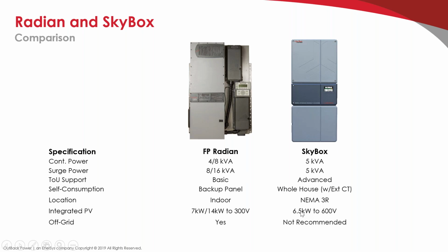The Skybox, you can have up to 6.5 kW connected at 600 volts. There's two PV inputs, but they're parallel inputs. So it's like two strings of 600 volts, but it's a single MPPT.